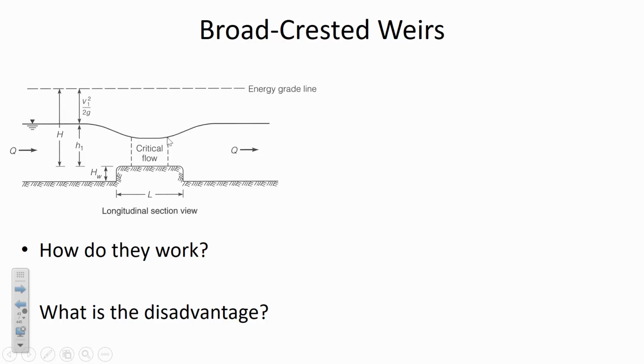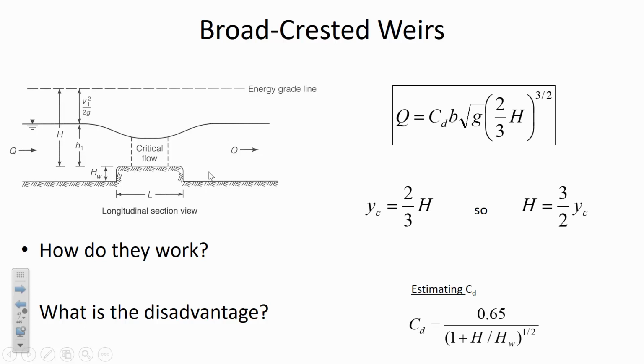By definition, to induce the critical flow, you have to have an obstruction that causes pooling. And there may be situations where you can't afford for the water elevation to get any higher, like if the canal or the channel that you're using doesn't have any extra height available in it for the given flow rate. So there are a couple of disadvantages, but still they're a nice physical way to directly measure the flow rate.